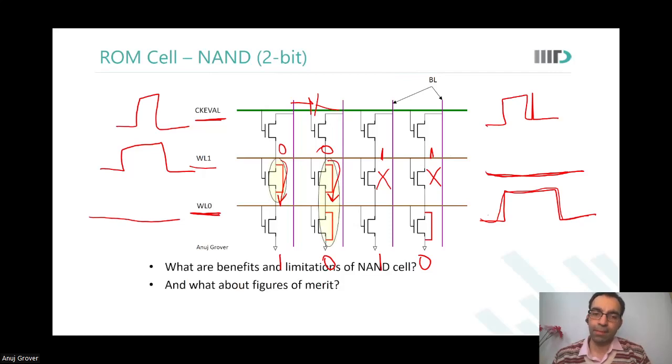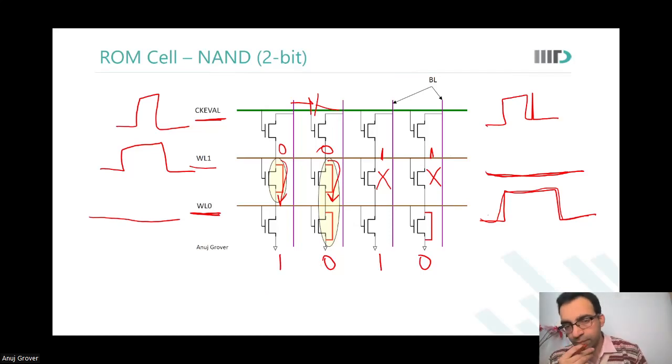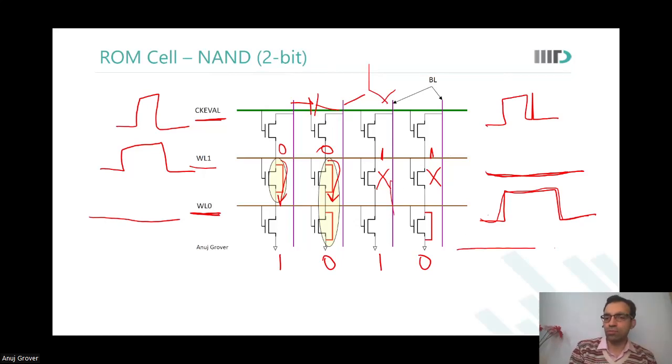He was saying that the inter-bitline capacitance would be significant because it is dense. For example, if I'm storing a 0 here and it's going to 0, and on the other side I'm going to store a 1, but since I don't have a connection there, why would that be worrisome for me? Because there is coupling happening between the 2 bit lines. You had assumed that this bit line will not fall, that it will remain at VDD. But due to coupling, it falls. But where's the path to fall?